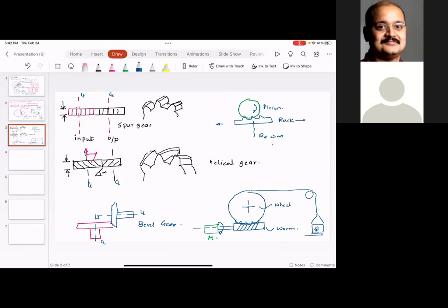Again, this depends upon the viscosity, and you have to be super careful with it. You don't want oil that is too viscous, because too viscous oil would increase the power transmission losses. If oil is not viscous enough, it will not maintain the film where the point of contact is occurring, so it will not help with lubrication. You want some sort of optimal viscosity, and that comes from something called the ZN by P type of ratio.